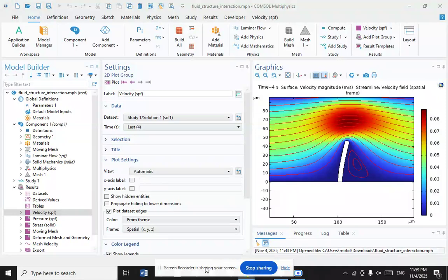The interface quasi-Newton method with the approximation for the inverse of the Jacobian from a least squares model couples a black box flow solver and a structural solver by means of the information that has been gathered during the coupling iteration. This technique is based on the interface block quasi-Newton technique with an approximation for the Jacobian from least squares models, which formulates the fluid structure interaction problem as a system of equations with both the interface's position and the stress distribution on the interface as unknowns.